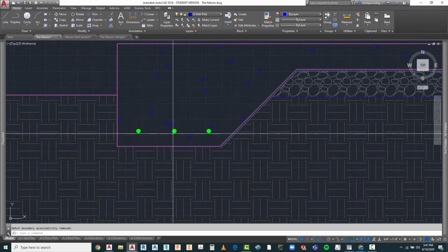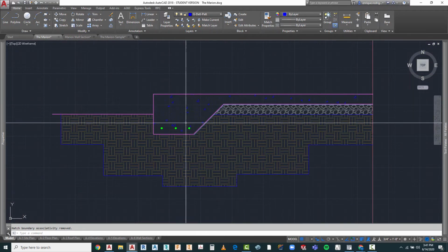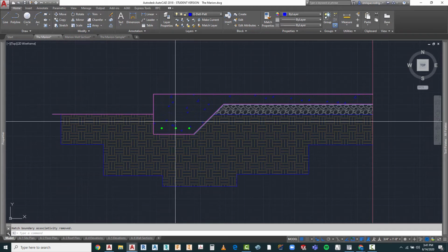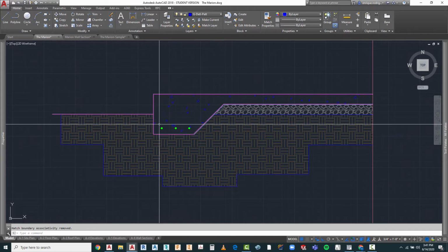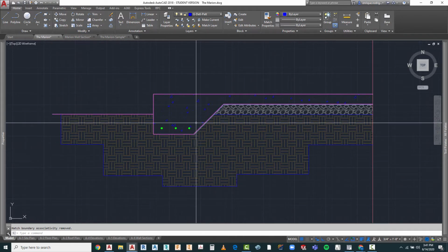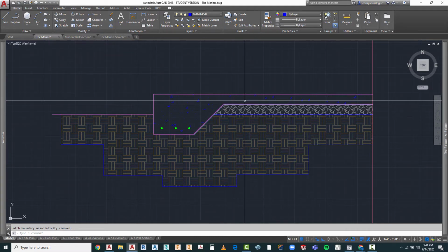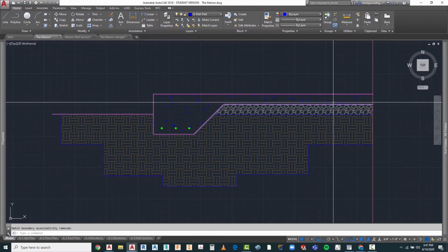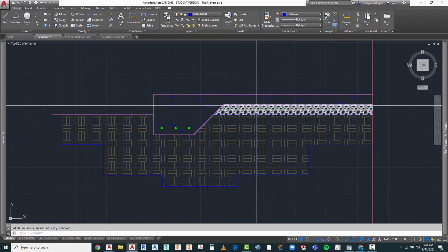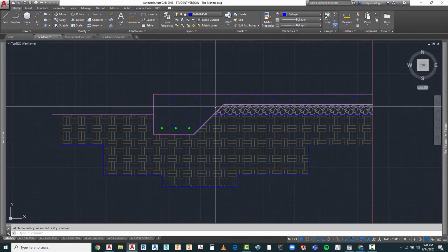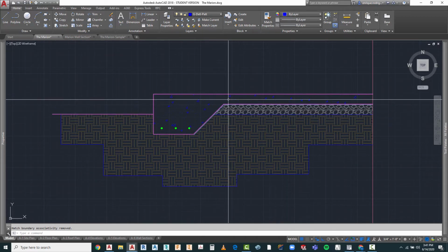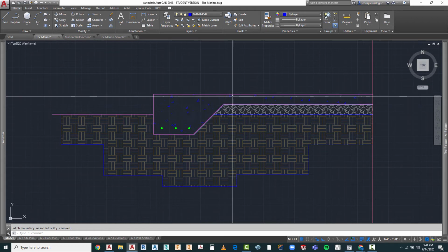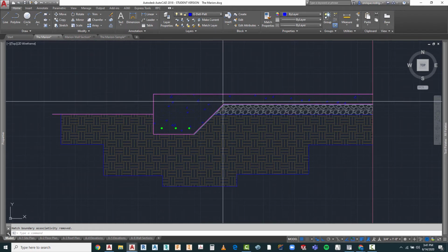So let's get these 3 horizontal reinforcing bars. We're going to have also vertical reinforcing, but for what we're going to show in this section, we're going to show those bars. And we're also going to show some welded wire mesh for the concrete slab. We're going to extend it about 60 inches beyond that condition.